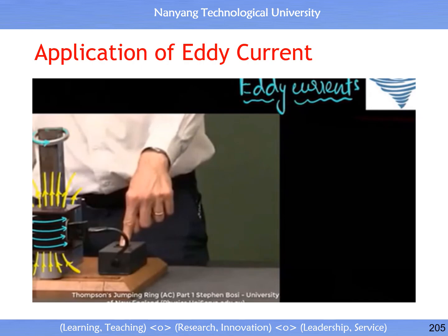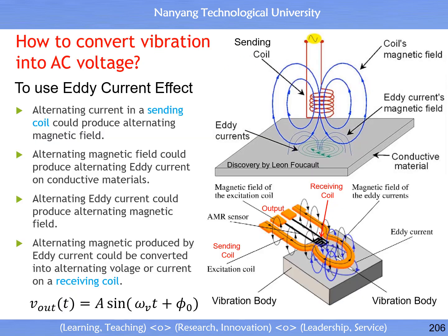But what causes levitation? Well, remember, this current loop itself starts behaving like a tiny magnet. So this aluminum ring now behaves like a magnet. And now from Lenz's law, we've seen that the current induced will be in such a way that it tends to oppose the cause for it. So when you apply Lenz's law, it just turns out that the magnetic field that it generates opposes this. And as a result of that, this starts repelling this magnet. And for that reason, once that repulsion is stronger than gravity, it starts staying in the air. Magnetic levitation. And one of